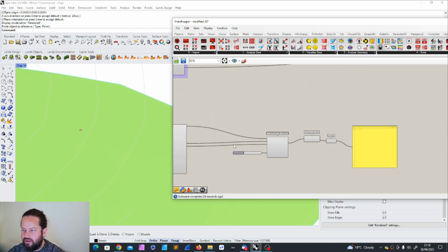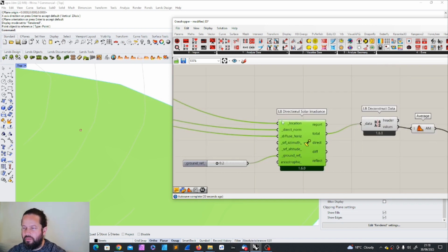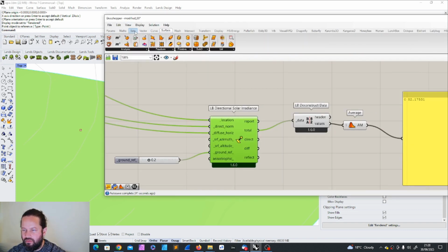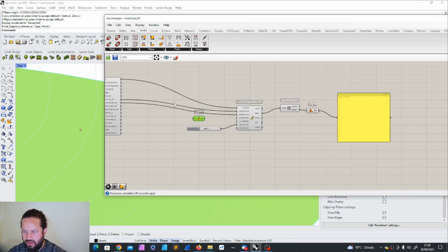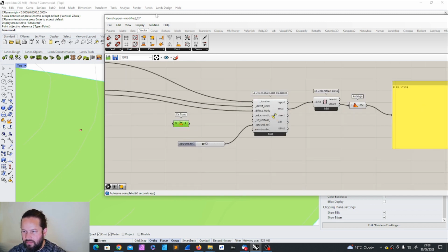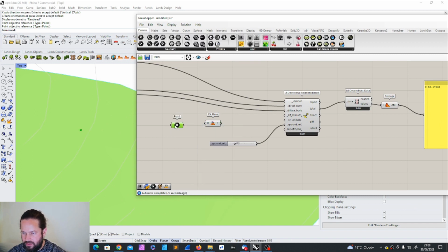And we use this point as the placement of our visual representation of that solar panel orientation. So we build everything in Grasshopper in this case. We can go here in vector. We use the XY plane, and I will explain why. I just want to make sure that I really capture the right orientation here. So with this one, this is my plane. It's not yet referenced anywhere, so I need to use a point. This is my location, and that I can place in here, and then I have my plane.